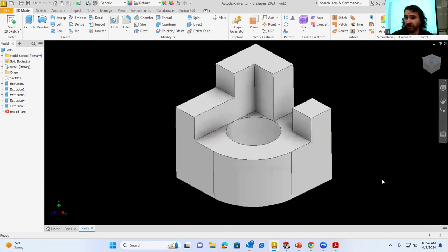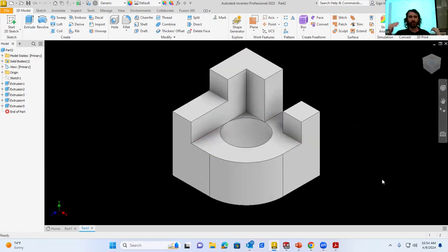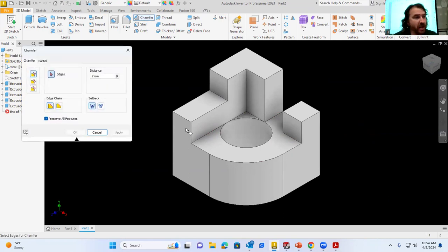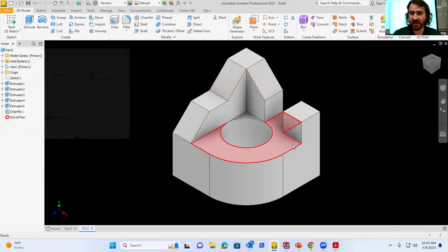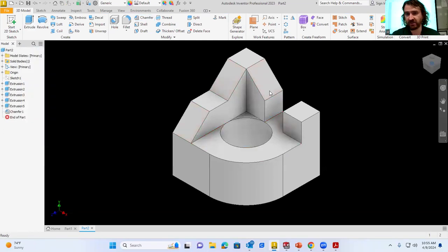And we're nearly done. So now we're looking at those chamfers, those cuts that were made before, right? We talked about adding those last. So this edge here gets chamfered the distance of 10. So does this one. And so does this one, right? So we can make sure we chamfer all those edges, those 3 edges right now, and hit enter. And that's it. That is the completed lesson 20.